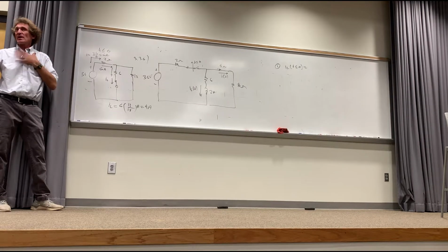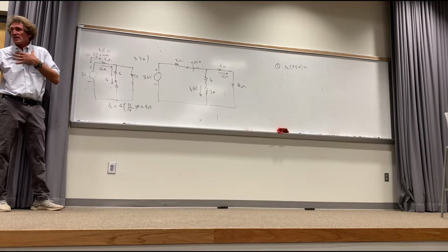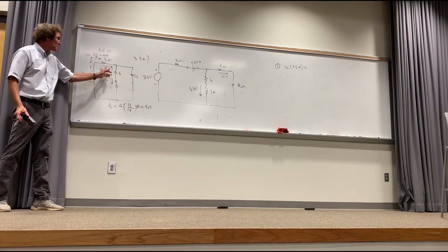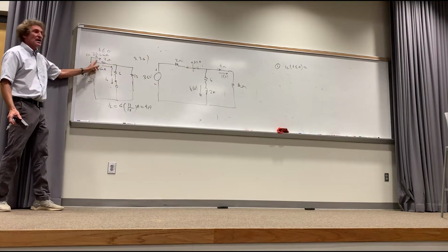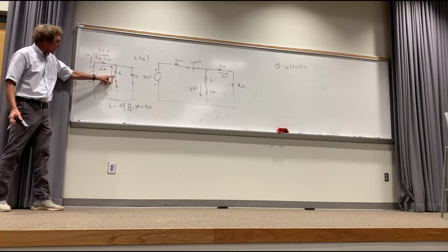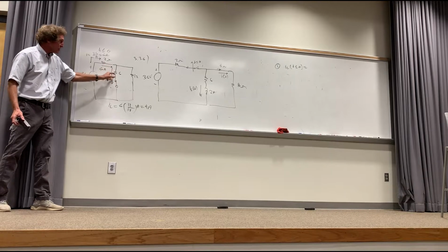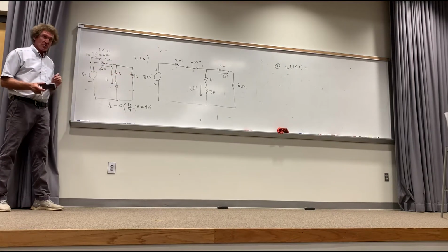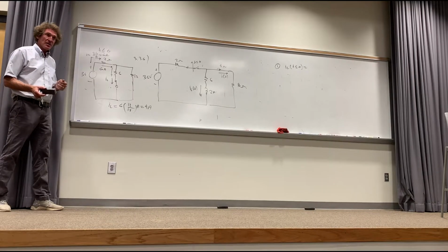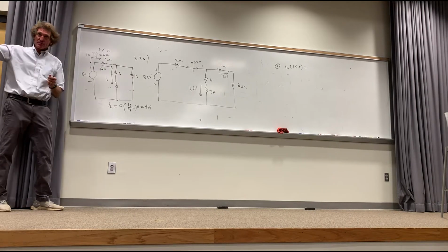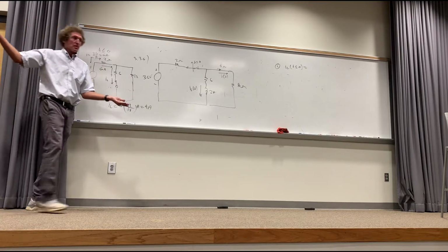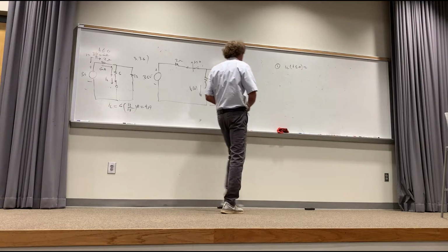But I'll tell you the way I do it, because to me it's the easiest. I would just take the parallel combination of those two, add it to 2, divide that into 36, then get this current. After I add that current, the amount of that current that goes here would be that current times 12 over the sum of the 2, which is going to be 18, and multiplying by 6. Got me on this one, class? How many see this right? But you can do it any way you want. So that means this is equal to 4 amps.